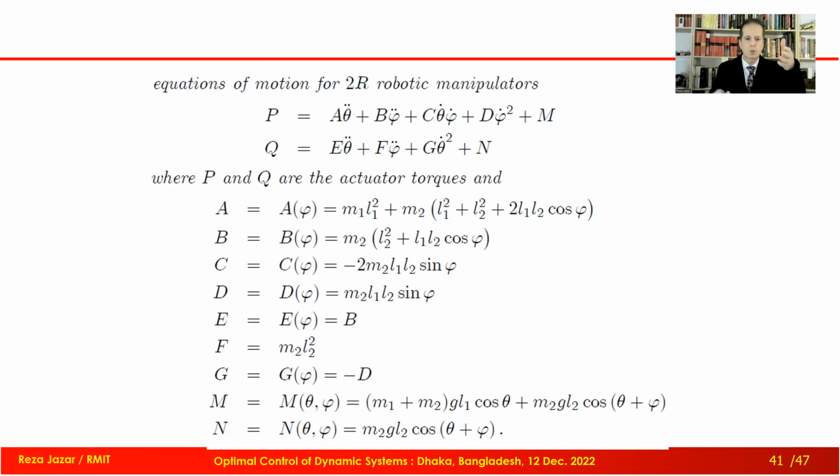I'm going to adjust them to set P or Q to be saturated. That's the way. In another step, we calculate again from inverse kinematics the new values of phi and theta, put them there, get new coefficients of the equation, and this loop is calculated to the end of the motion. One point: tau is just one-dimensional, related to time, so the same tau time interval goes to all of the equations. The P equation or Q equation, both of them have the same variable of floating time.